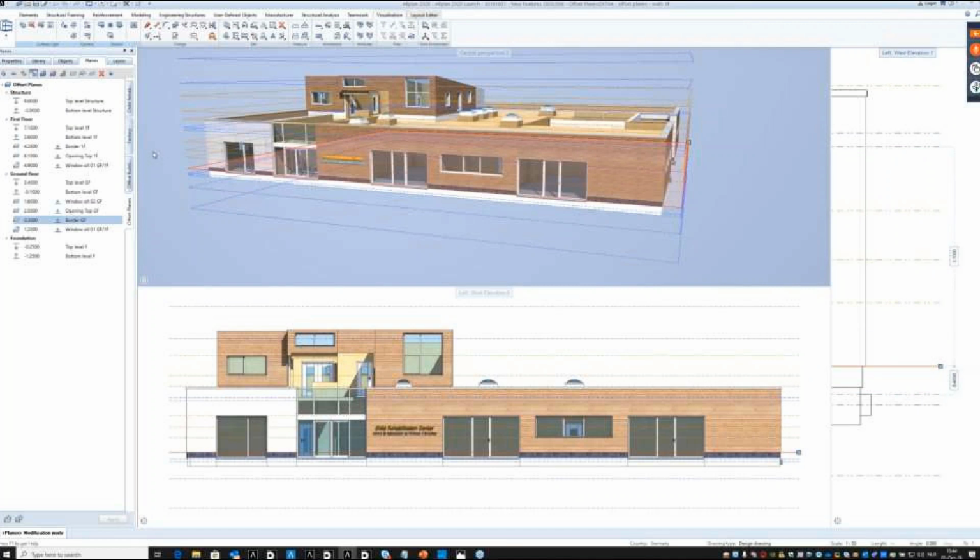the references update. So the idea is that sometimes it's not enough to have the top floor, bottom floor, the coordinate of each floor, but you would need some reference line so that you can control the geometry easily, especially when it comes to modifications. So for complex architecture as well, where you have some items higher than others within the same floor, this is an excellent solution.